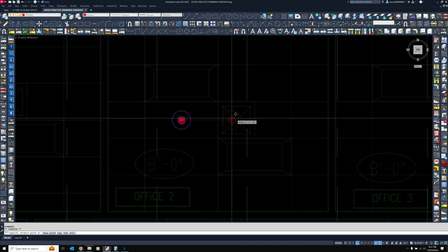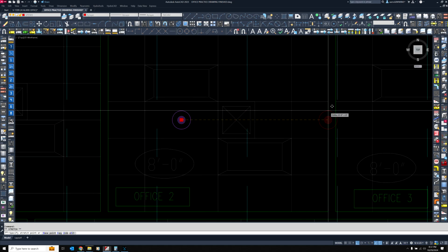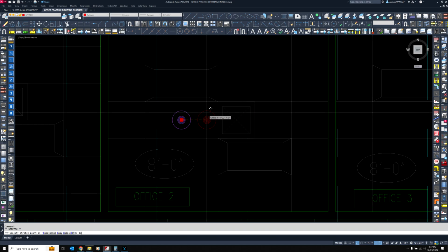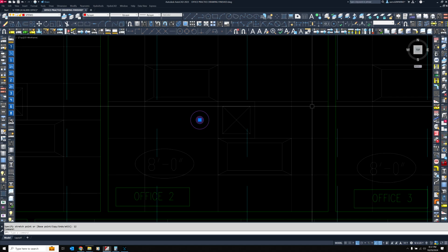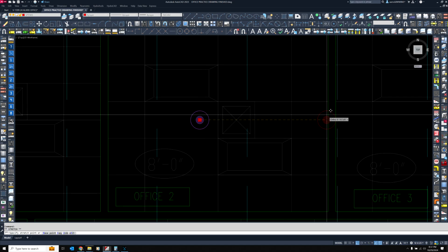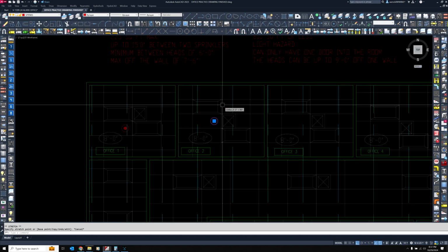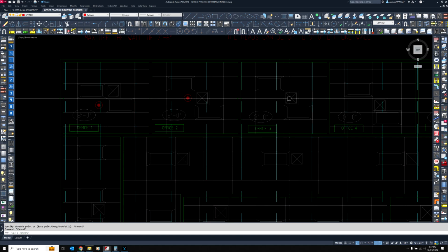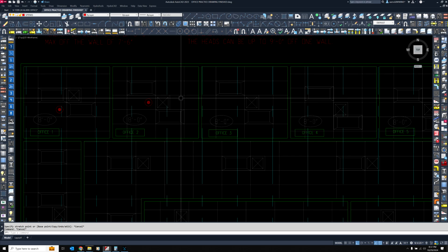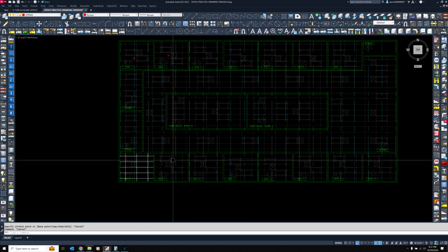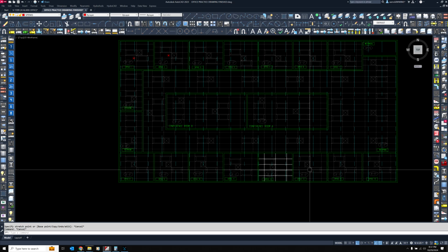And while we are legal with the small room rule, we can always pull it in and require less water if we go 12 inches to the right. And now we are under our 7.6, under our 7.6. So this is how you're going to space heads through the rest of this room, rest of this building. Your offices duplicate the layout.